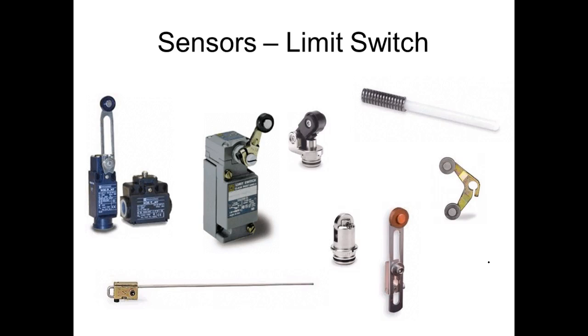And these are real high current things. It had fallen off. So when they opened up this thing to turn off the motor, the motor never turned off. So it would go up and jam up the things and kick the overload. And we got up there and saw what was going on, and the thing was arcing. And we blew it out. We actually blew it out. And then we remounted the thing that did that. So DC is hard to extinguish.